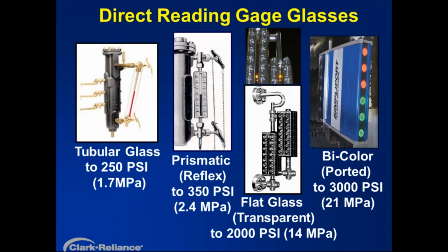And you'll notice the two sections in the image overlap each other. The reason for the overlap is that it is an ASME code requirement that dates back to 1996, and that requires transparent type gauges, because water would show as clear and steam would show as clear, to display so that the operator never loses sight of the meniscus line. So as the water level rises in that lower of those two sections, it will carry over into that upper section, and no matter where the level is in that operating range between the two sections of glass, the operator never loses sight of the level.